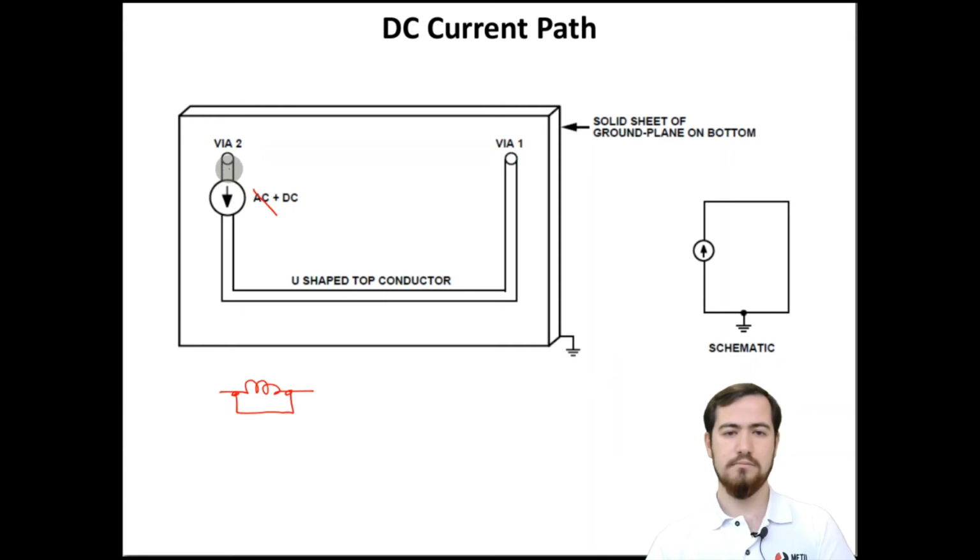We know that the current should follow this path on the top layer because this is the part where we have copper, but for the bottom part we need to draw our layout, and let's think about different types of layout designs. Let's say I had put some path such as this one for returning current on the bottom layer,